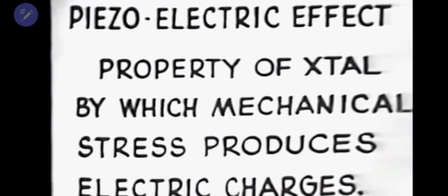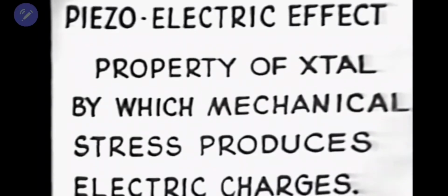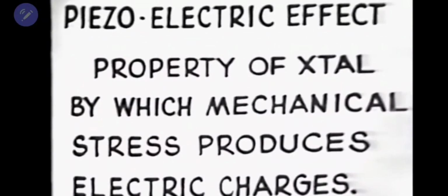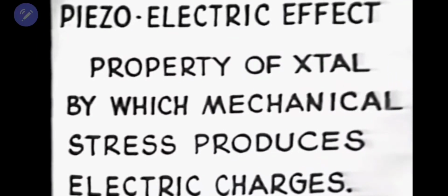A crystal used in oscillator circuits must possess a characteristic known as piezoelectricity, or the piezoelectric effect. Now, the piezoelectric effect is defined as the property of a crystal by which mechanical stress produces electric charges, and conversely, electric charges produce mechanical stresses.